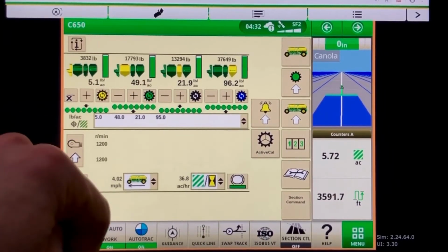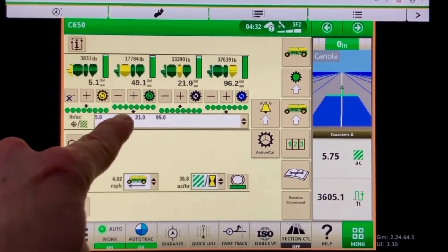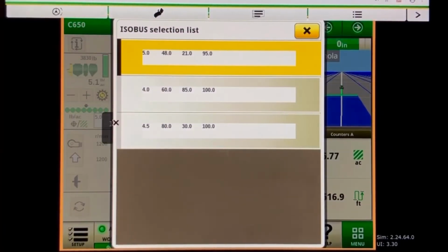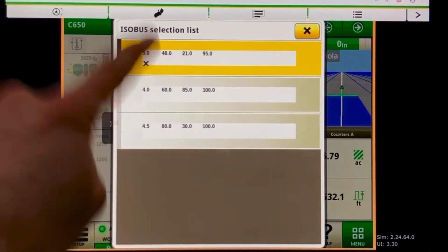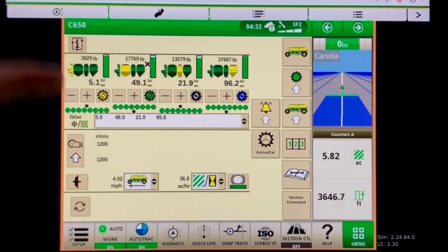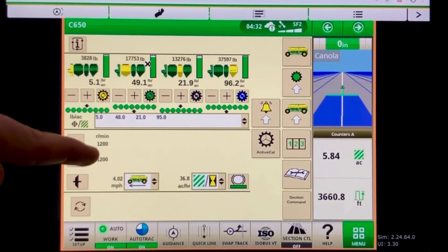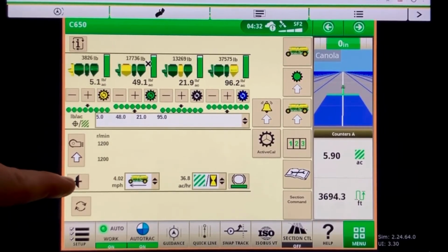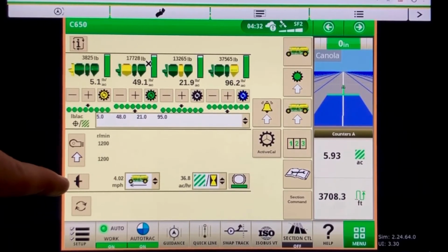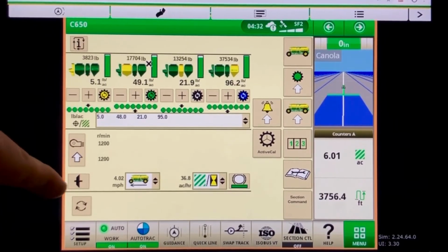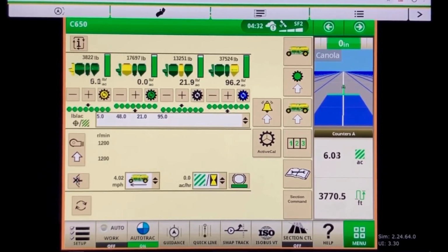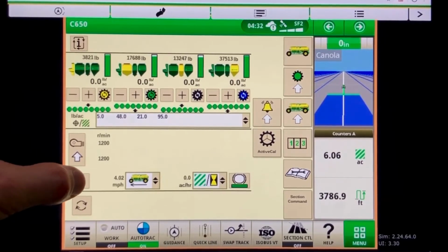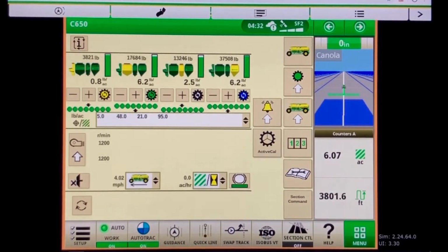Next, we have our pick 6 here, where as we showed you in another video, if I simply depress it, I can choose between those 6 preset rates that I want to have dialed in on the machine. Here, I can set my fan limits as well as I have my current fan speeds being displayed. Down here, I have my manual clutch control. Typically this is operated by section control or by a master switch or an implement switch on the machine. But what I can do here is simply depress it, and I can take manual control of the clutch being on or off on the machine.